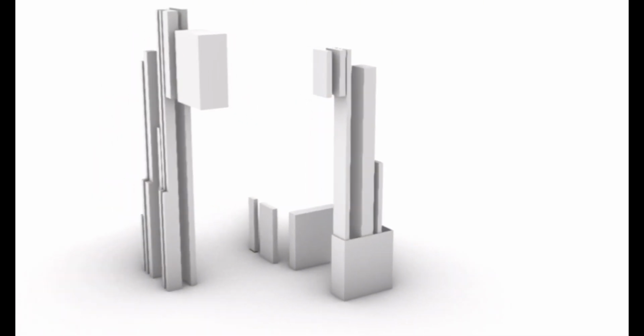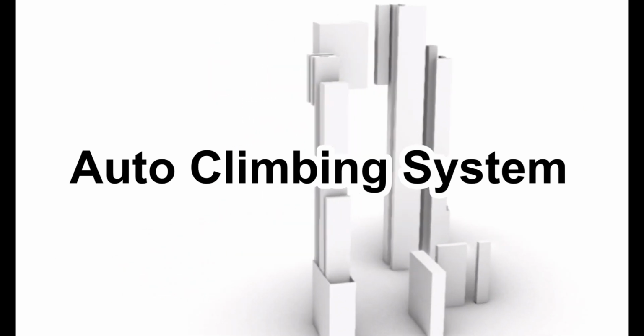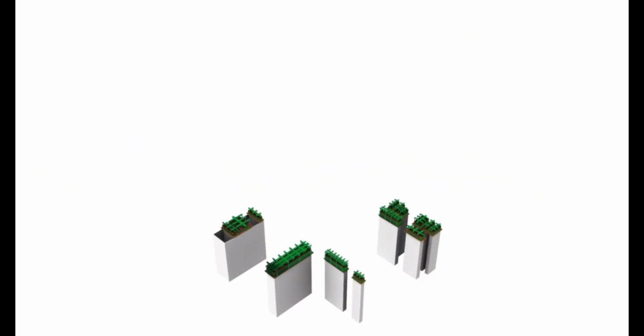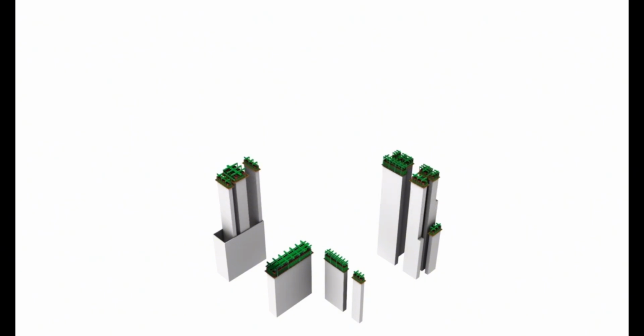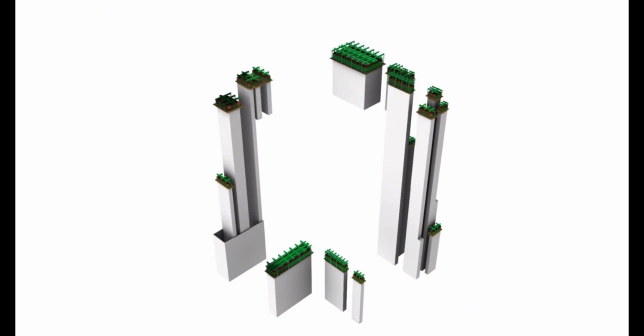In this process, an auto climbing system was used for construction workability when placing concrete on the outer wall of the core. Since the cross-section of the core is not constant, a new formwork was needed to adjust to the changes in each cross-section. Therefore, in the part where the cross-section of the core changes, a flexible climbing formwork system was applied that disassembles the formwork and reassembles it according to the cross-section.